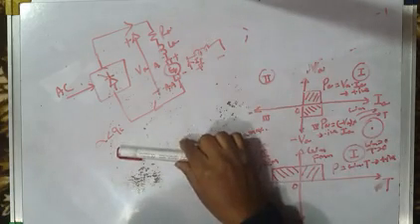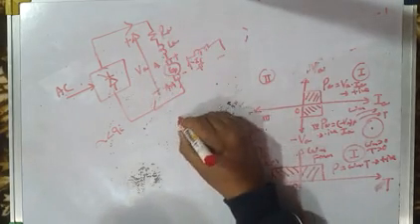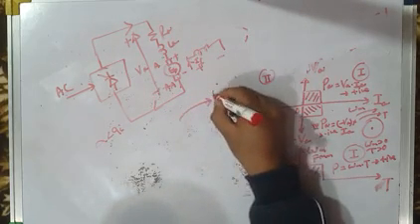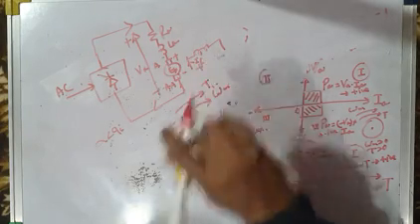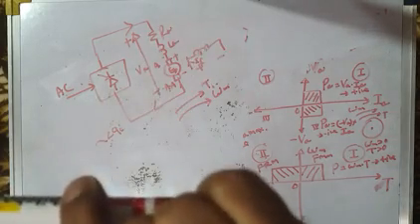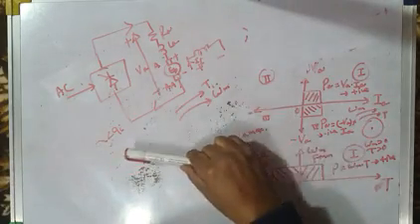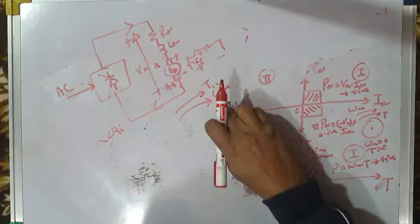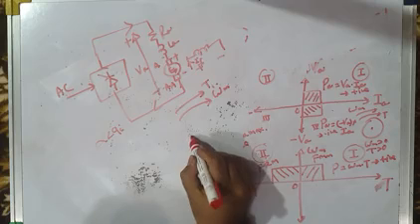And see, when the cage is moving from ground floor upward, the motor is running in this direction, the clockwise direction. Torque is also in this direction. Okay, like this. At the 20th floor, it was an empty cage. At the 20th floor, now we have loaded the cage. Now we have to move it down. When it moves up, the motor runs in the clockwise direction, and when it moves down, the motor runs in the anti-clockwise direction.